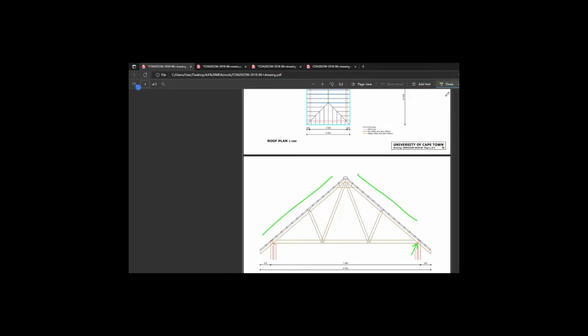You see in this drawing, actually, the wall plates have been indicated. And the only thing holding these trusses down, other than their own self-weight, their own dead weight, is the hoop iron that we're going to add now. I'm not exactly sure, but one end goes in that side. It might go over both the tie beam and the rafter, and I don't know how many times I loop it, but it's long, 1.5 meters long.